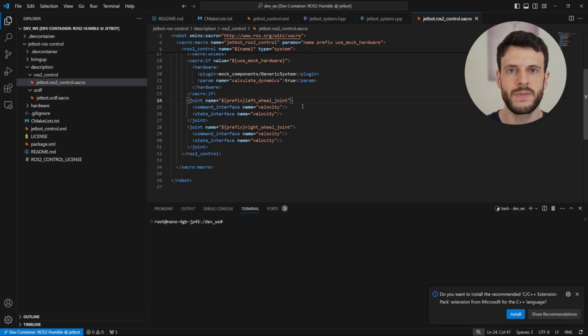But as we saw in the previous video, we specify a value from -1 to 1 that we write to the motors in order to move them from their maximum reverse speed to their maximum forward speed. Therefore, we want to write from -1 to 1 to our motors. We also have a state interface of velocity where we report the measured values from the motors. However, we don't actually have anything that's measuring values from the motors. There's no encoders and no other sensors here. So really, we're not actually reading the velocity, which is why that read method earlier did nothing.